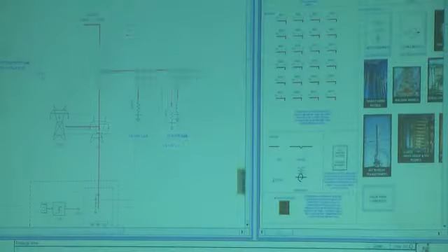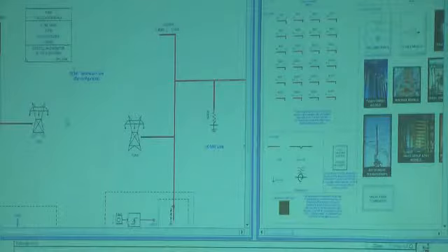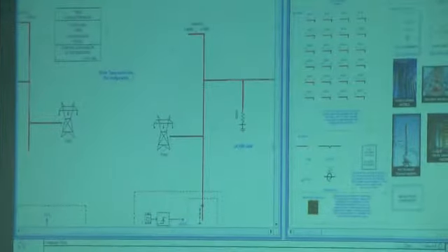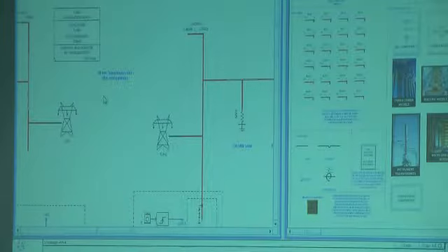So I'm going to show 2 different options of how to split the network. When you have more than 72 nodes, we have to split the network somehow, and we do that at the transmission line. So you may remember from the first training that the transmission line needs to be a minimum of 1 time step long.